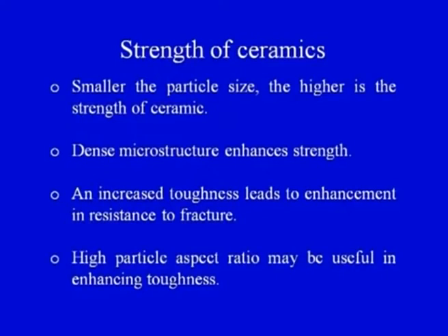So, basically there we will address how the size of the particle would affect the mechanical properties of the ceramic product. When we make the ceramic from the powders, the properties of the powder would affect the mechanical properties of the ceramic product. Dense microstructure enhances strength. Yes, if the porosity is less, we will get better mechanical properties. And increased toughness leads to enhancement in resistance to fracture.